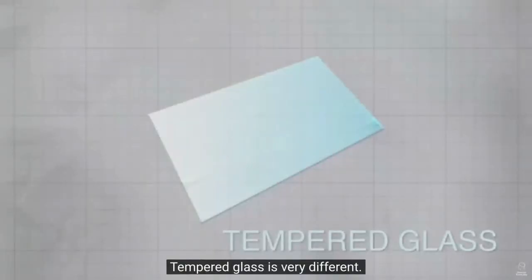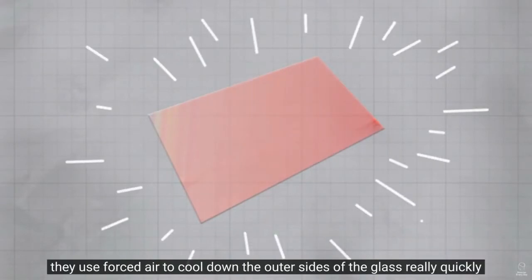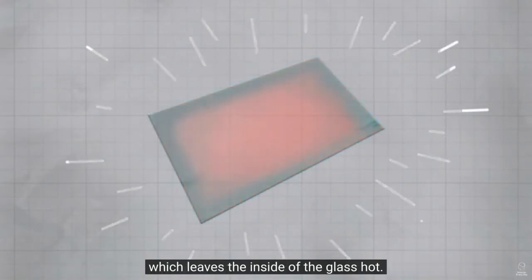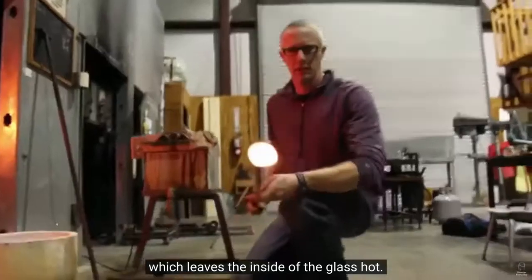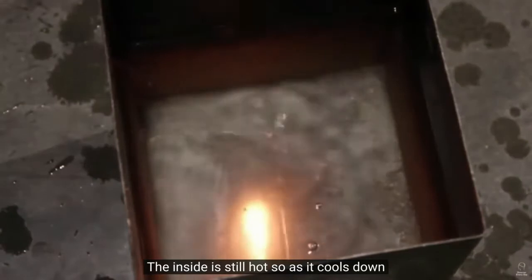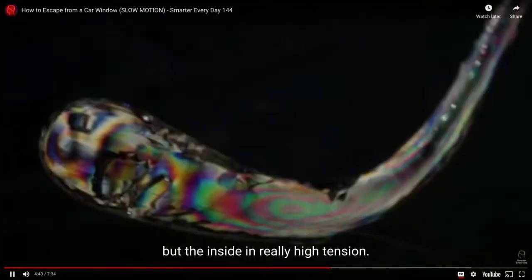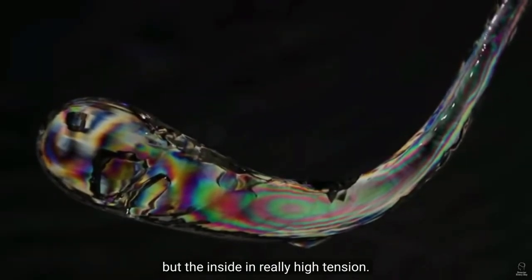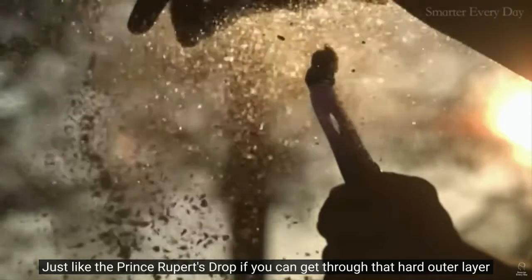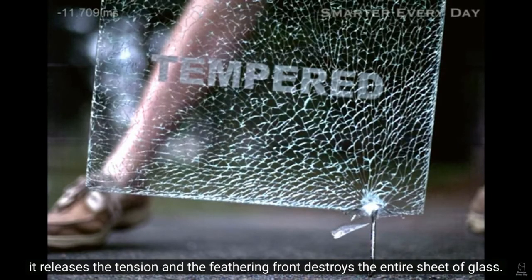Tempered glass is very different. Instead of allowing the glass to cool down slowly, they use forced air to cool down the outer sides of the glass really quickly, which leaves the inside of the glass hot. Kind of like how a Prince Rupert's drop is made if you remember that video. The inside is still hot, so as it cools down, it shrinks and pulls in, which puts the outside of the glass in compression, but the inside in really high tension. Just like the Prince Rupert's drop, if you can get through that hard outer layer, it releases the tension and the failure front destroys the entire sheet of glass.